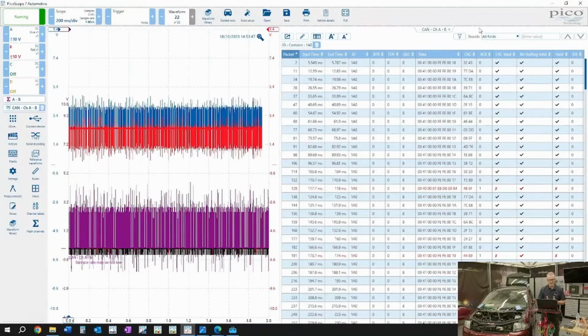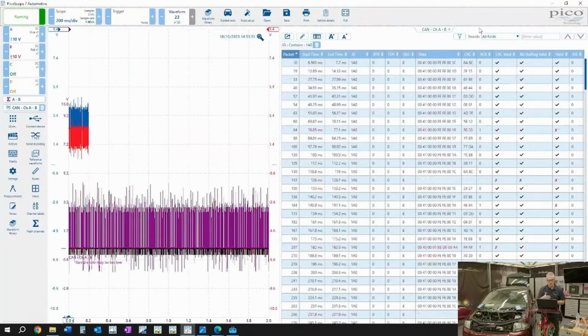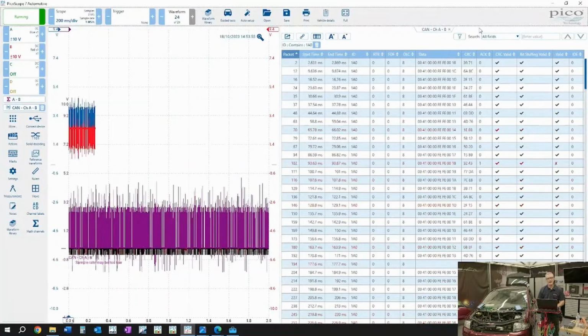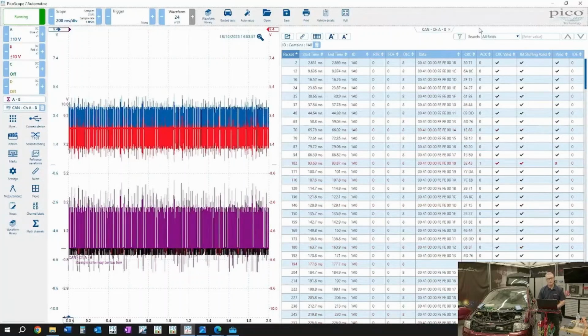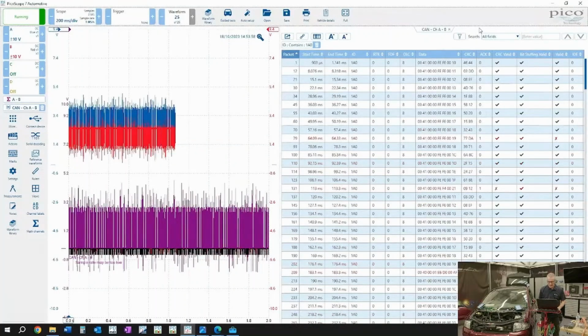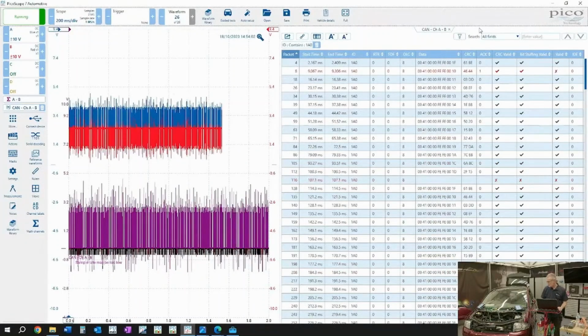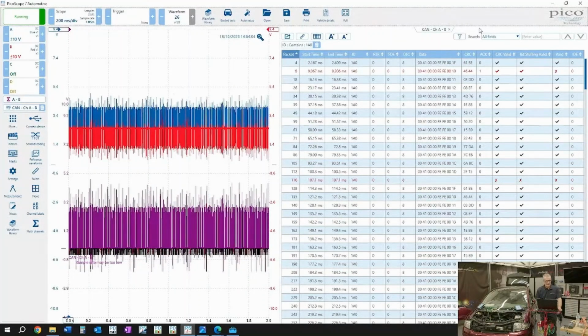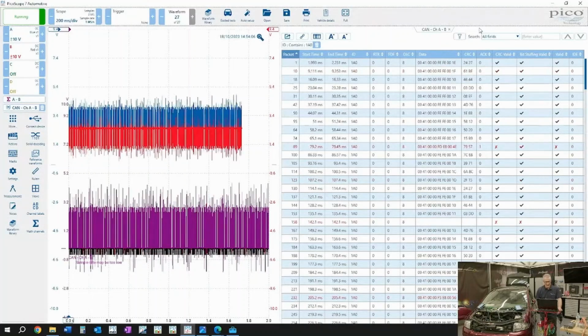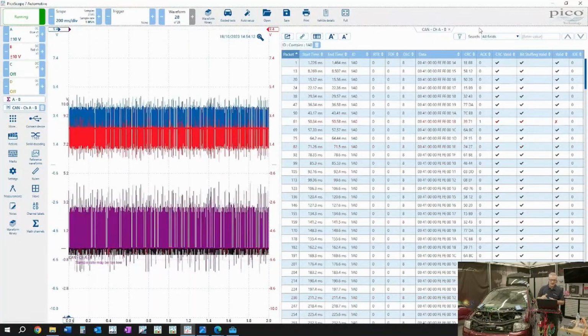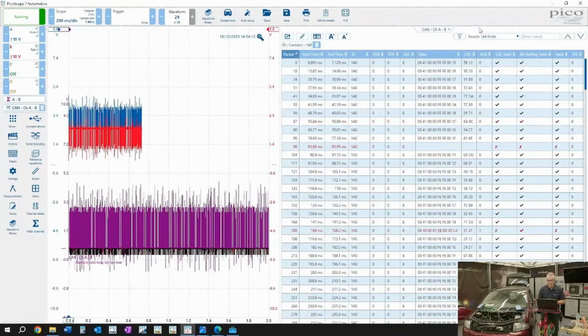So that's great. We're still collecting all that data. All other IDs are still being collected behind the scenes, but we can see that 1A0 is the only ID we're filtering on. What I wanted to do now was just simply disconnect the ABS ECU. He says it like it's easy, and it is. It should be. It was working in rehearsal. Let's see what happens when we're filtering for 1A0.